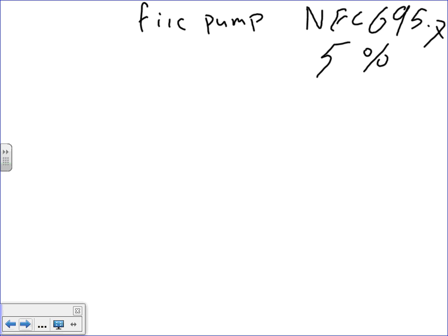Why? Because if you have a fire and you're fighting it, do you really care about the voltage drop? You have the fire raging in your building, and you say, "Oh, no problem. Drop the circuit that feeds the fire pump because it's not working efficiently." It's the least of your problems, voltage drop. So they allow you to go 5%.